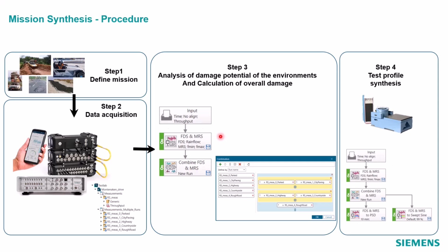And then if our part or component is going to see multiple of these environments in its service lifetime, we will add those fatigue damage spectra in series. And so we've added a kind of a nifty graphical way to do this in the software, so we'll be sure to show that. And then from there, we want to synthesize an accelerated PSD from the fatigue damage spectra. And this PSD will have an equivalent damage to the lifetime field data.